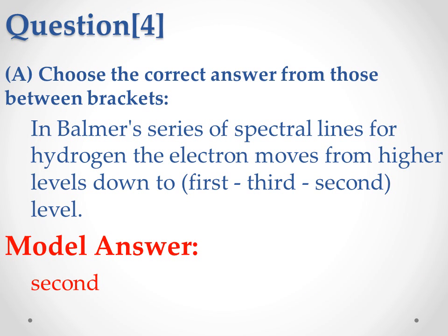Explanation. Backward bias connection. P-type is connected to the negative pole, and N-type is connected to the positive pole. The field due to the battery is in the same direction as the internal field. The depletion area increases. The resistance of the P.